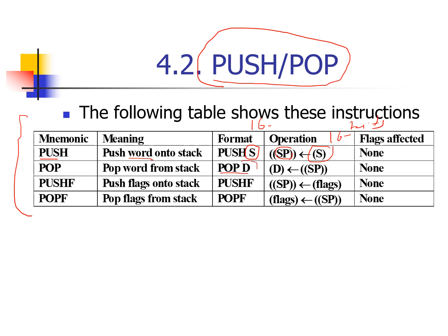You have to specify only a destination with pop. This will take 16 bits of data from the stack. These 16 bits of data are pointed to by SP. You take these 16 bits and put them back into whatever destination you wish to store your data in.